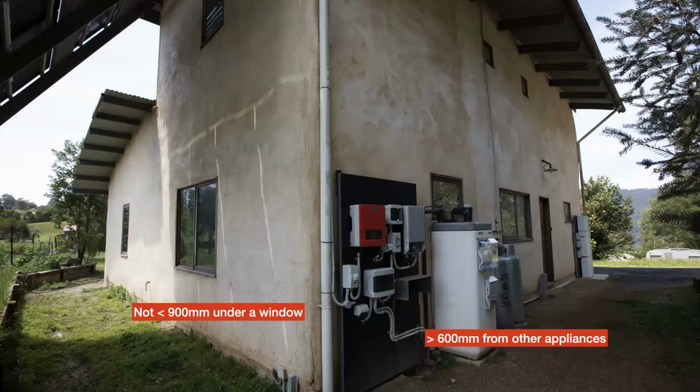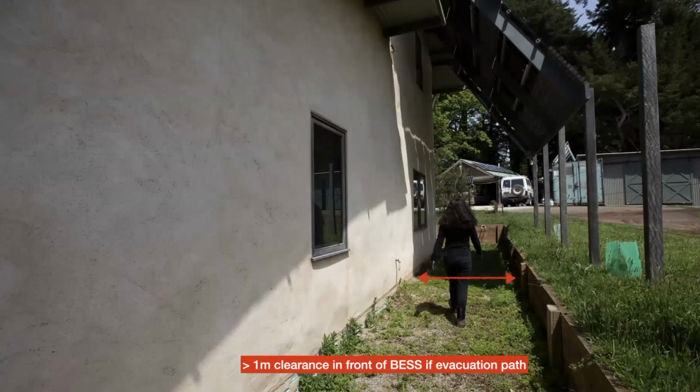Underneath that shaded area, possibly. I still have to stay 600 mils from a window. So there's probably one location along that wall that I could put a battery system. Incidentally, I'm actually planning on putting one there. And I've got to still consider that access. Is there 1 meter of clearance if I put it there? Well, in this case, yes, but only just. 1 meter is a lot.